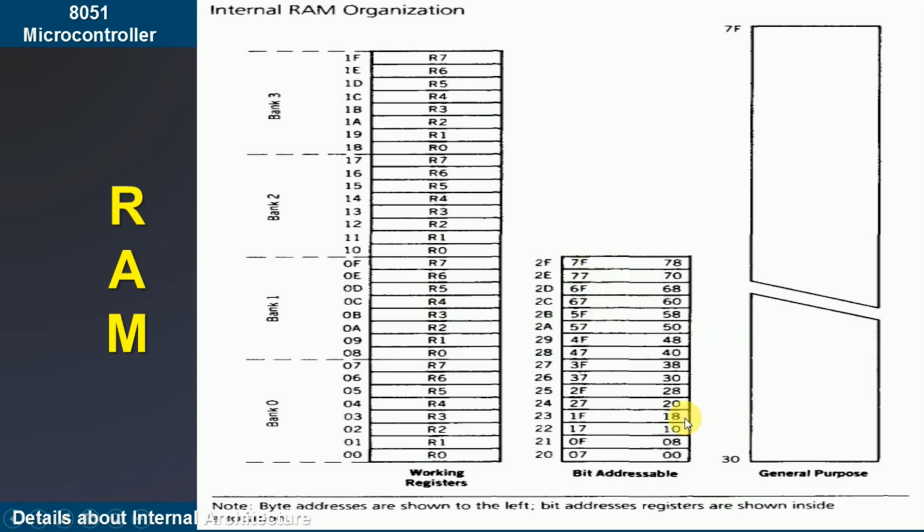Now, as I told you, there are two types of information. The first example which I have already given: when I have to measure the temperature, first we measure it by a thermocouple. So, what is the output of a thermocouple? Millivolts. Very correct. That millivolts, by using a signal conditioning circuit, we convert into 0 to 5 volt. That 0 to 5 volt, by using ADC, we convert into digital form, and that digital form of 8 bit data we get from a port, and we store it in the bank area. This is one type of information that we get from the external environment.